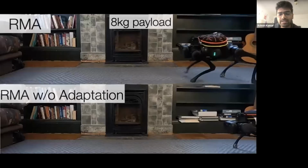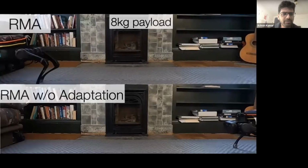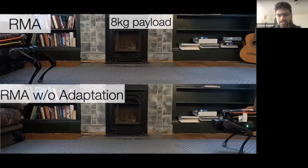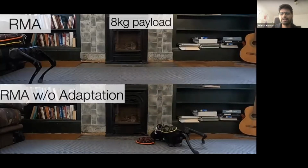So this is an 8 kg payload. The manufacturer comes with a 3 kg payload limit, and the weight of the robot is 12 kg. So this is roughly 70% of the weight. And when we switch off the adaptation module, you see that it struggles because the center of mass has changed, because the weight is slightly uneven and it's more tilted towards the front, and that gets to the robot.